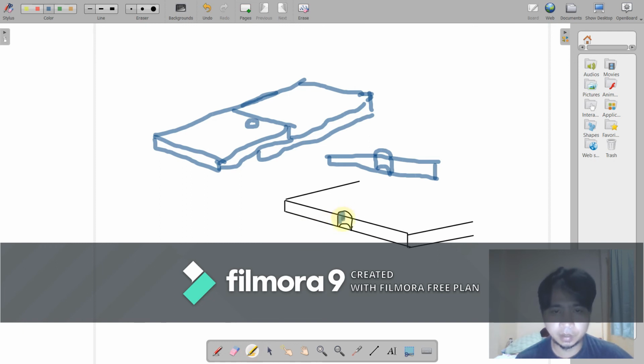So this shaded portion here. Okay. So that shaded portion there is actually what? Half of the circumference supposedly times the thickness. So the bearing area is equal to half of the circumference times thickness.